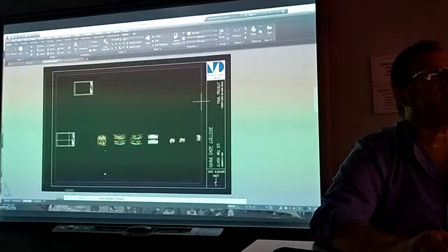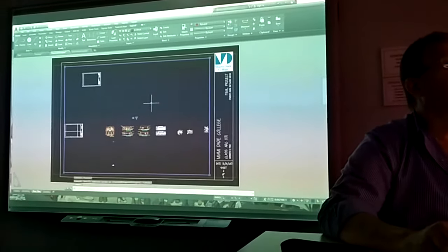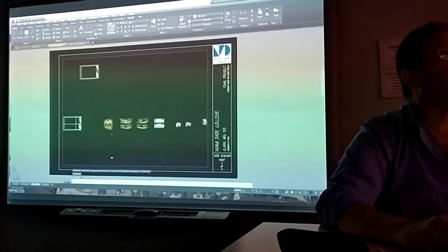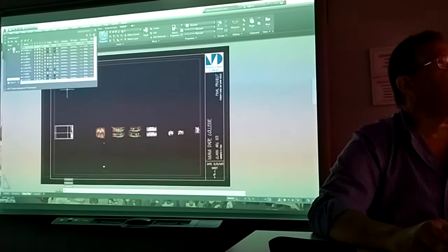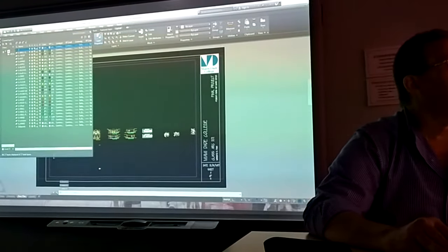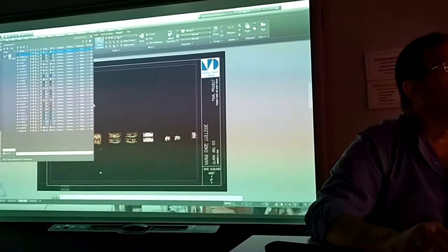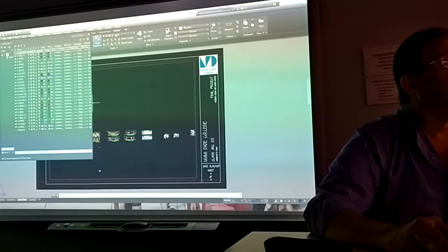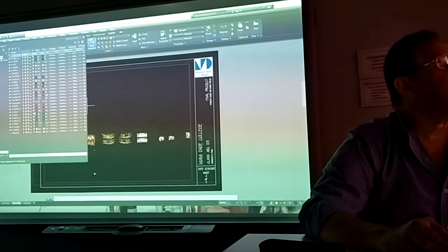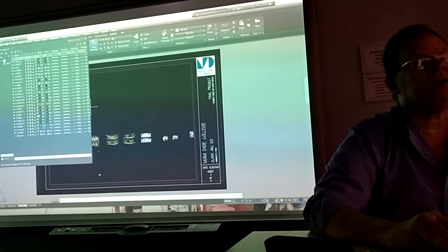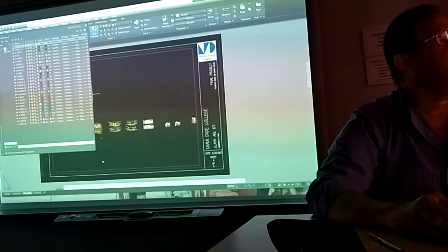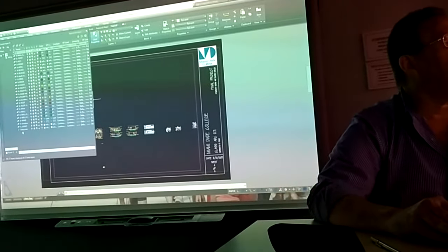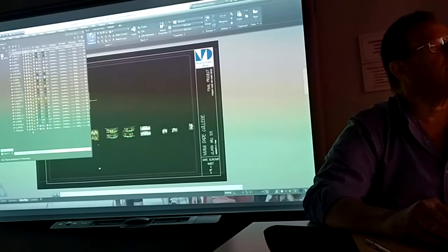Now magenta, it's not gonna print. I just want to make sure if you go to Layer Property Manager and you open up this window, you want to make sure that the printer is clicked. No printing. Right there. See the little print with the circle and the slash in red? Okay, so that's not gonna print. Or I could use depth points. It's not gonna print either.